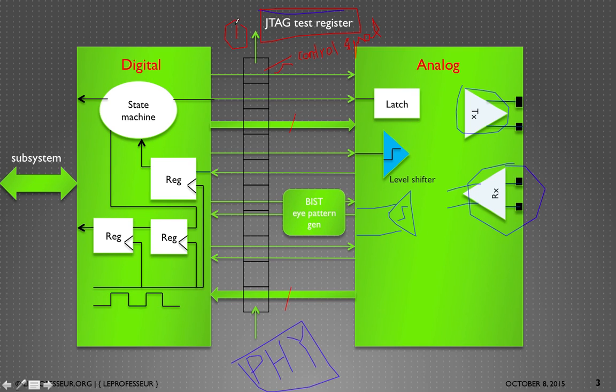Now the second important thing is the synchronization. The signal from the analog portion is coming to your digital portion. Before using that signal, you must synchronize it. Typical synchronization happens with double back-to-back registers. Here I just put one drawing, but typically it's double back-to-back registers, a synchronizer or sync block.